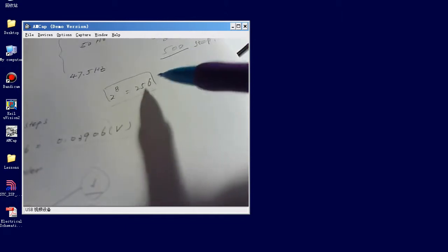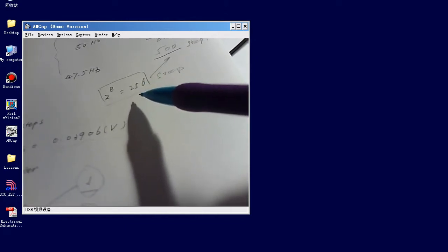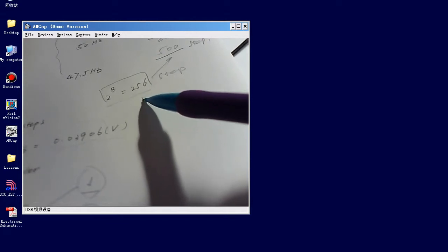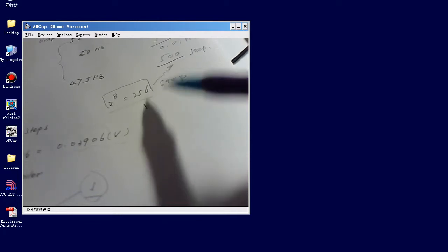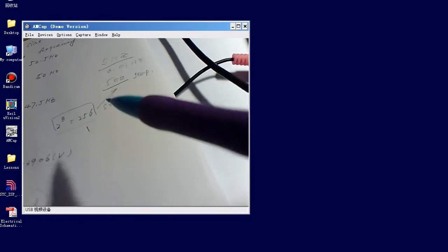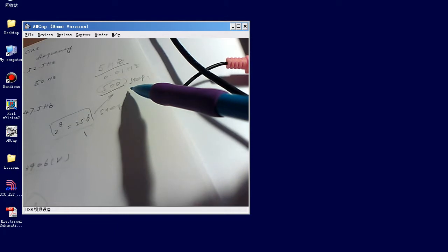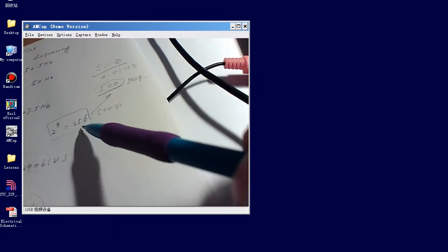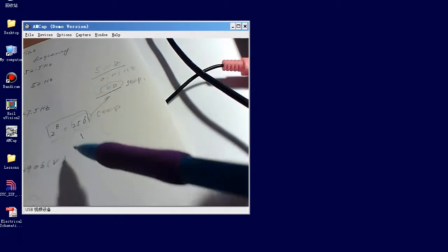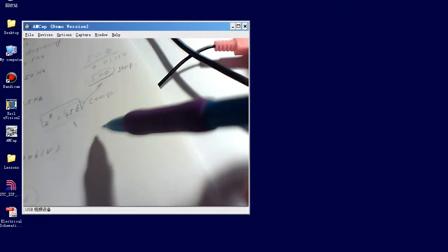So in other words, for each individual step, no matter whether it's increasing or decreasing, the function generator should give us a corresponding value, because the frequency resolution of the function generator is much finer than the analog to digital converter's resolution.